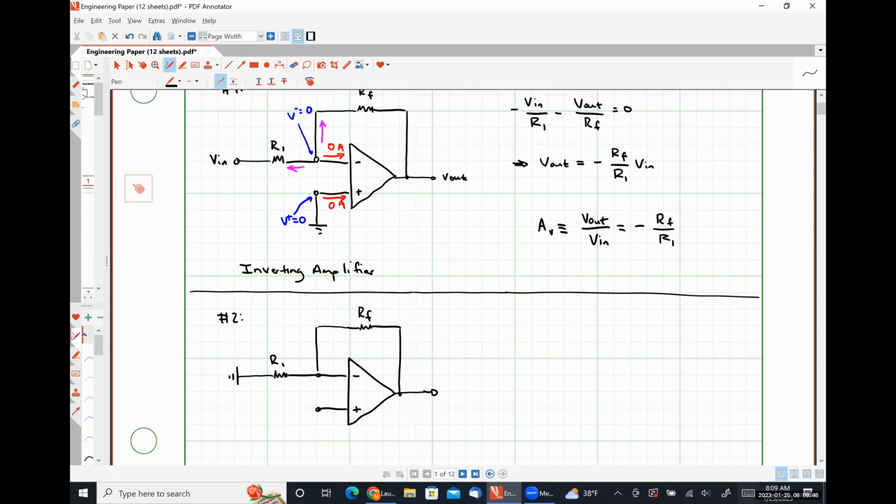So for this particular circuit, we are going to ground the terminal of R1 where we had just placed our input voltage. And we are going to apply our input voltage at the pin that we had previously grounded. So we're literally just swapping these two, Vn and ground. In this configuration, you have what I'm going to call a non-inverting amplifier in a moment. We'll see why. You switch them back the other way, we have an inverting amplifier. Okay.